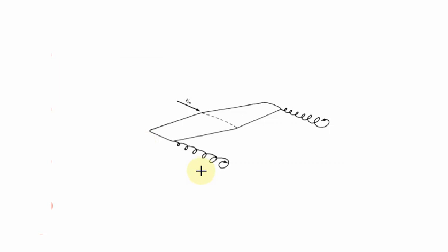Suppose you can see this picture clearly. This is happening for the aircraft exactly. Here also it is happening like this. Each and every portion of the trailing edge faces that problem. This is called trailing vortices, because it happens at the trailing edge; this is a leading edge and this is my trailing edge. It is happening like this, and the one at the tip is called the wing tip vortex.